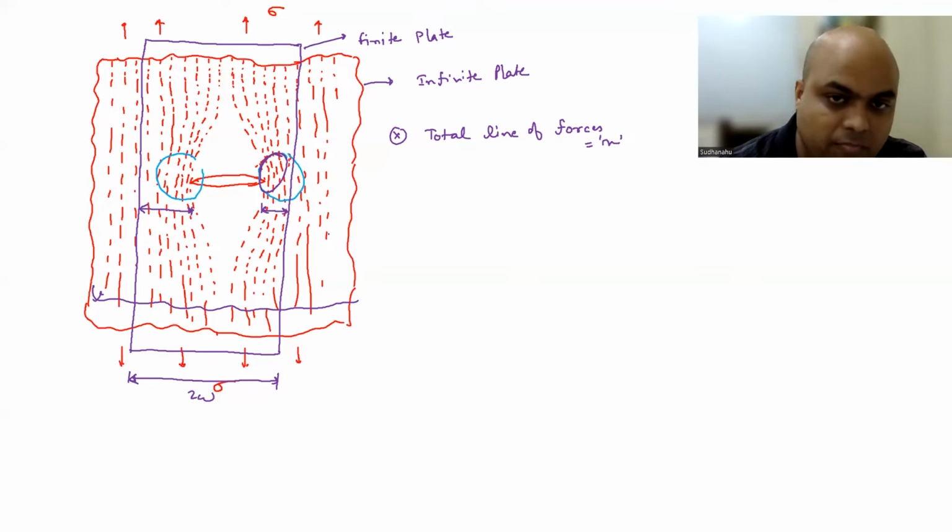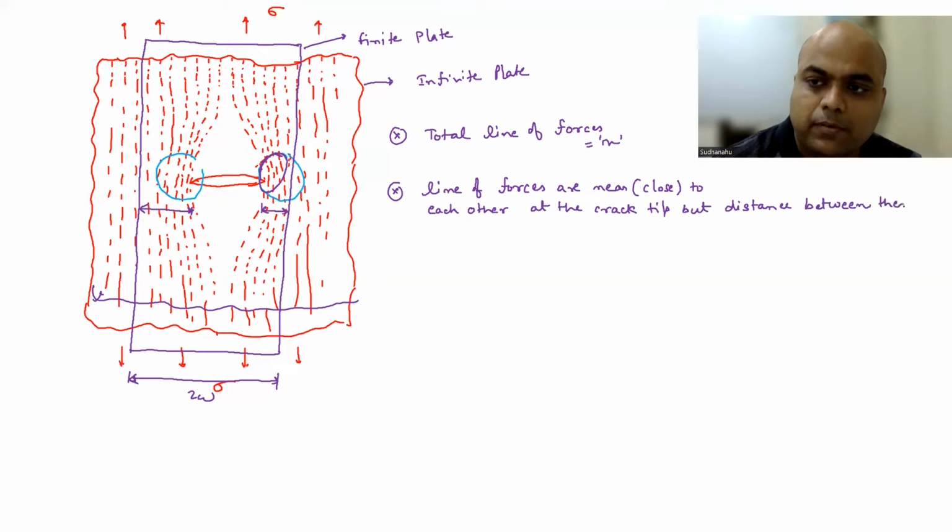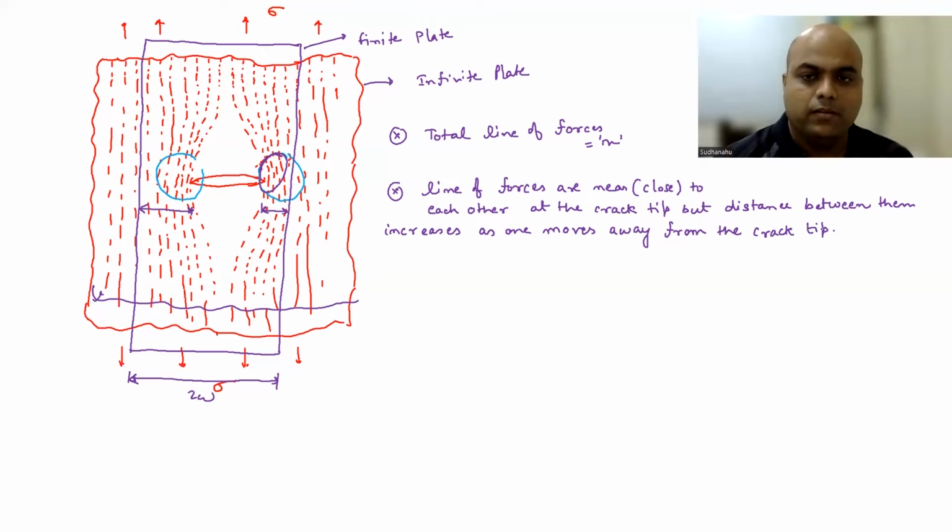So lines of forces are close to each other at the crack tip, but the distance between them increases as one moves away from the crack. So that is point number one, and that leads to the stress concentration.